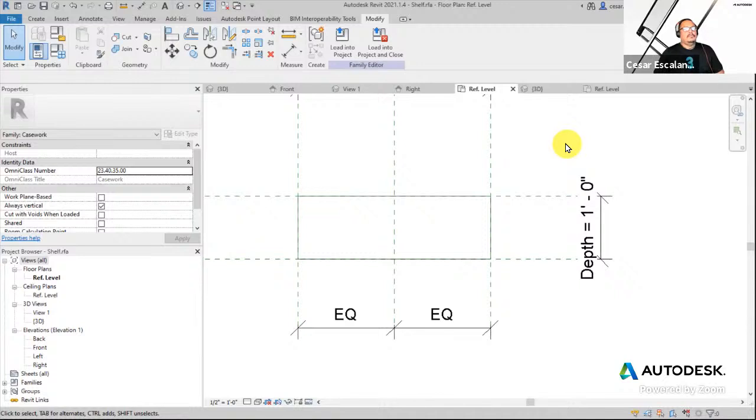No, but you need to be aware of them, because when the nested components are placed inside another one, the origin only defines how that element is brought into the other family, but you can always lock the faces of the nested family to other reference planes so that the origin doesn't have an impact on how the element flexes. And so it's really up to you.